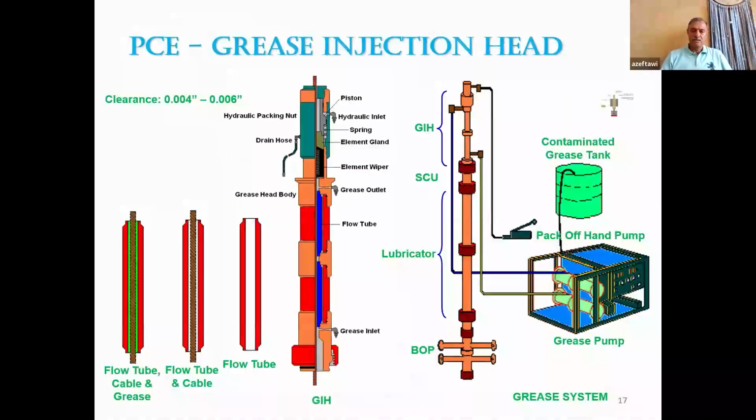Back here to this rig up. I said it is a closed circuit, clockwise direction. This is the closed circuit. Some other companies or some other people use an open circuit. Open circuit means they pump the grease, it goes through the grease inlet, but the grease outlet goes to a container and they throw it. They don't inject it back to the system. This is the open circuit.